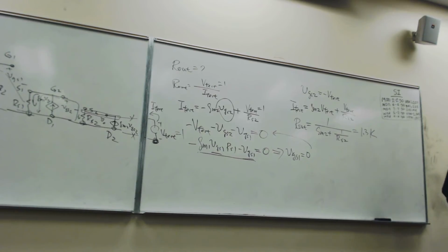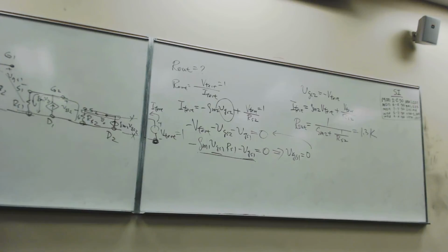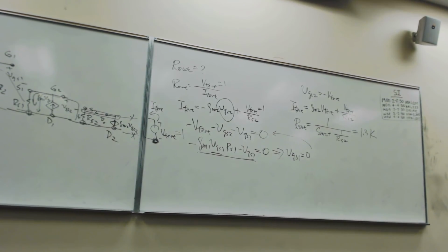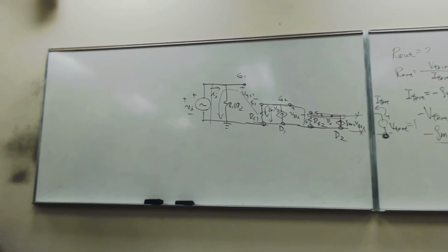Good. Good finish. Now let's go to the maximum output swing. Before we do that, I will have to figure out what are the DC load line and AC load line, yes?